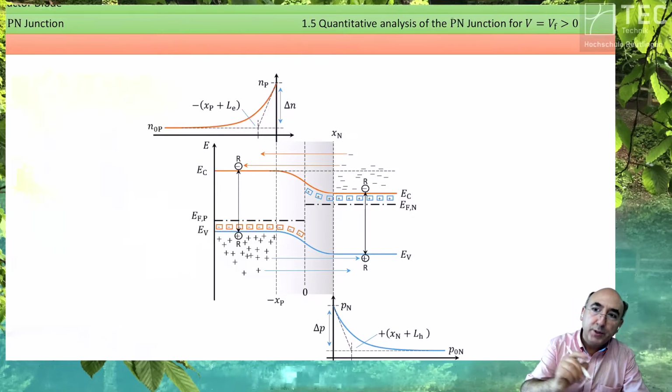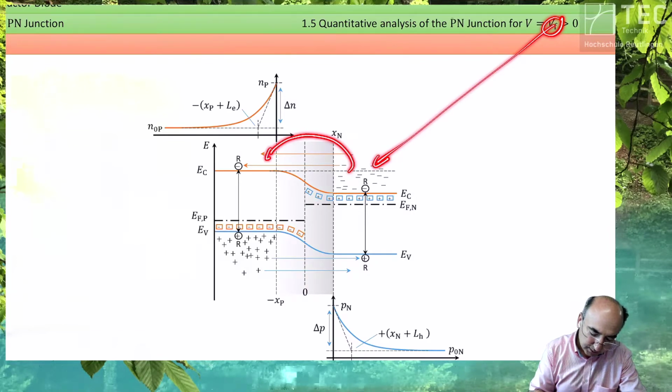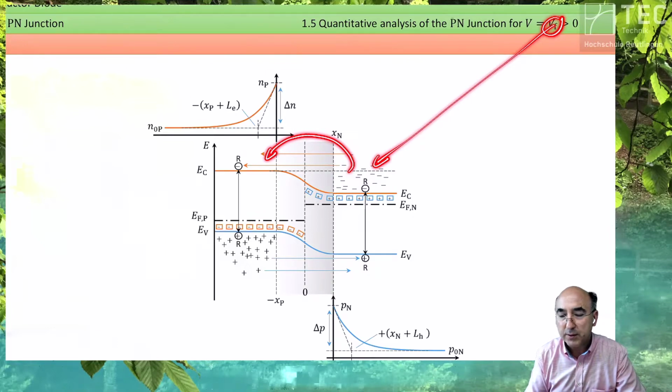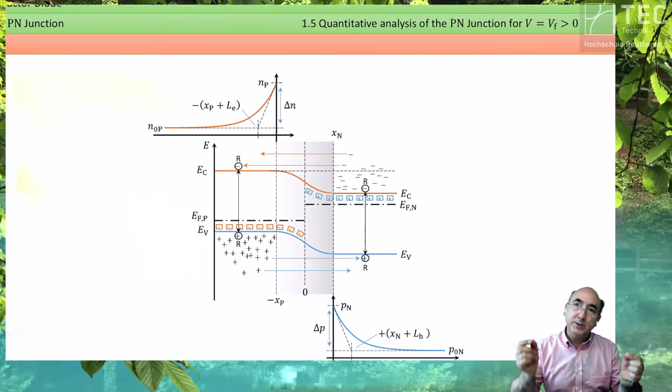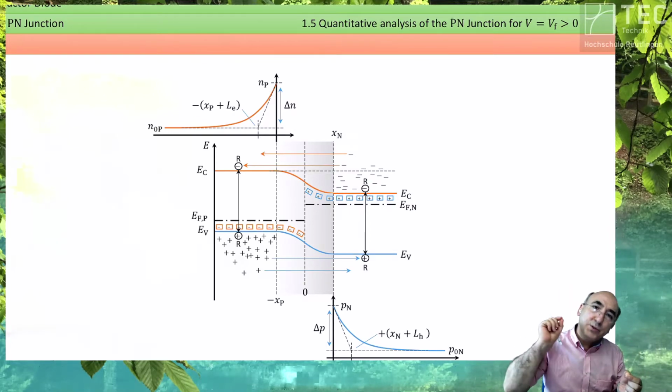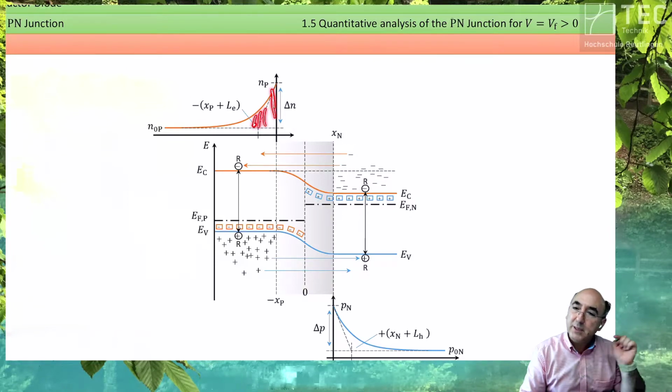This stored charge appears only if you apply forward bias, due to the fact that for forward bias, you just start this injection. So if you want to have a diode let the current flow, you store charges in the diode. You can't avoid it for PN junction diodes.